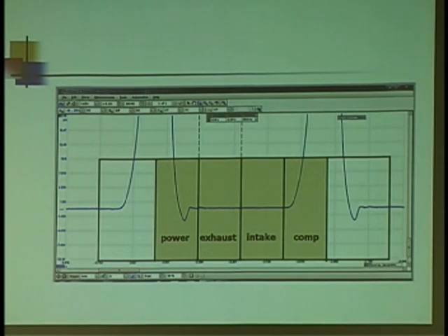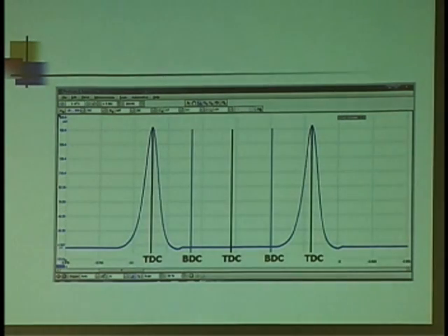Well, this is just running. I want to know, if I have all this air in the cylinder, and I have the same air in it when I get back to bottom dead center, shouldn't the pressure I started with be the pressure I ended with? In a perfect world, is that cylinder perfect? Is there always a little bit of loss? Okay, that's what you're seeing. We're going to lose a little bit, okay? So that when I do get to the bottom, I'm actually in a slight vacuum. And that's no big deal, but it is a key.